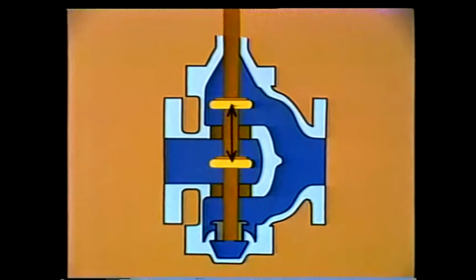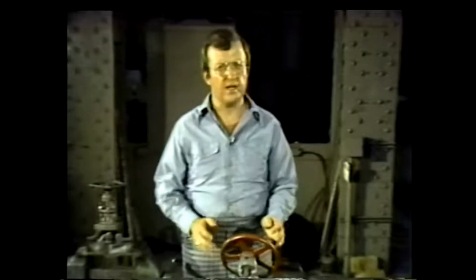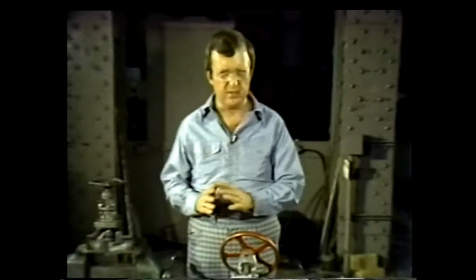Now, they're especially serviceable where system pressure is very high or where constant adjustments must be made to control the flow through a valve. This is a piston balance valve. The double disc arrangement on this valve allows the force exerted across the seating area to be as equal as possible while being directed in opposite directions.